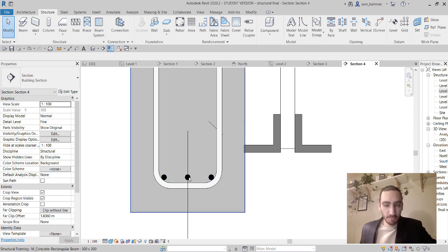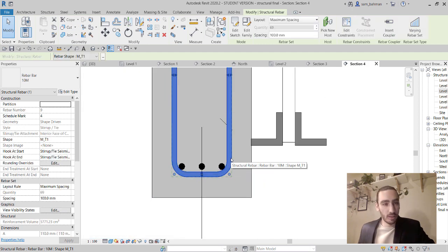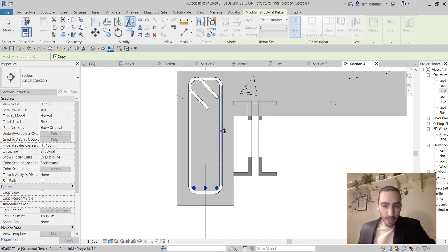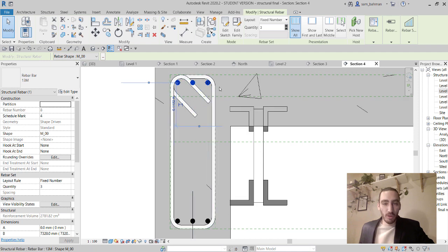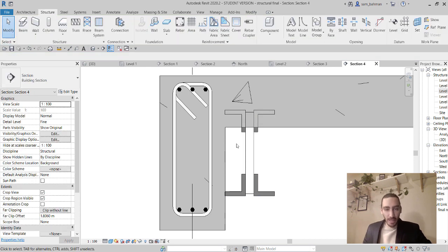Now, as you can see, the rebars are all working well here. We don't need to shift them. So what I need to do is simply choose them. Let me make sure that they are on 13 in terms of size. All right, we're all good in terms of size. Now just choose the lower longitudinal rebars, go for the mirror, and make sure to put the midpoint for the stirrups. So I believe there would be the midpoint for the stirrups. So simply draw the sketch, the axis, and as you can see, the top rebars are all getting placed perfectly.